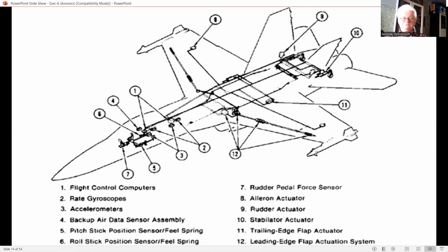It should be noted that the inertial excitation forces are in antiphase with the aerodynamic excitation forces, as the angular acceleration of the vibrating control surface is 180 degrees out of phase with the angular deflection. So both components are taken into account in assessing the structural coupling effect.